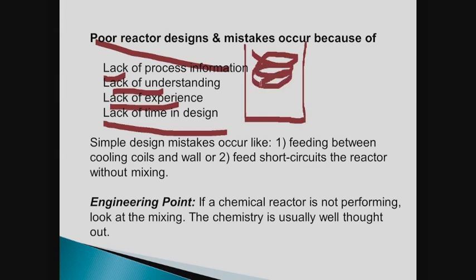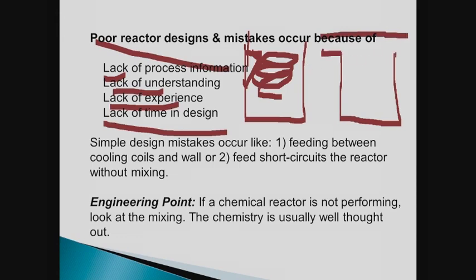And the heating coil is pretty dense, and you feed right here between the coil and the wall. That's asking for problems, because that becomes a significant dead zone. Or this one here, basically the material comes in here, flows across the top of the reactor, then leaves, never participating in here.